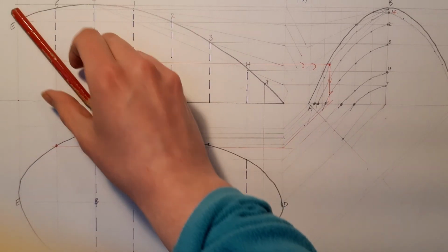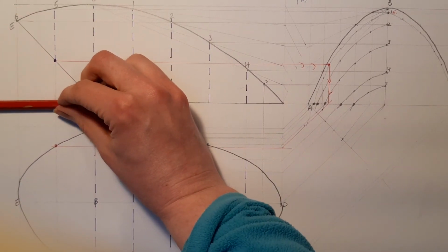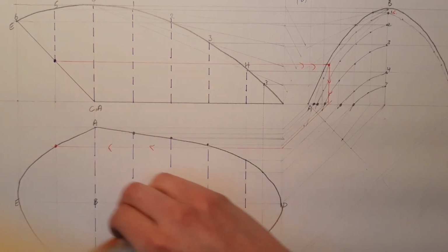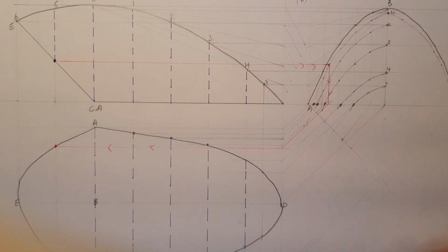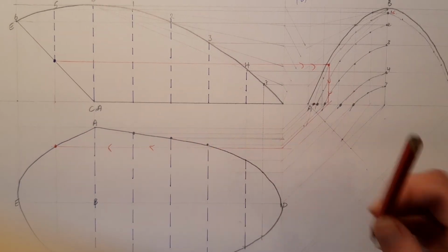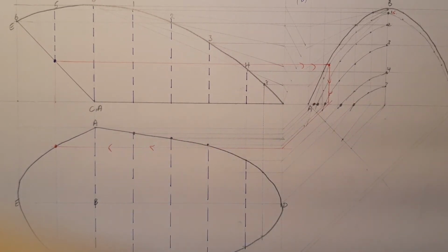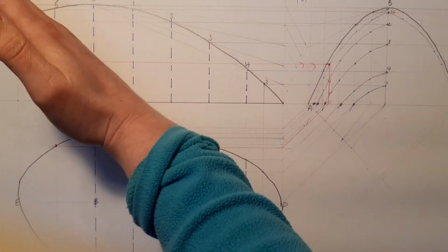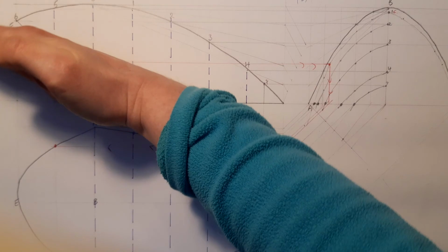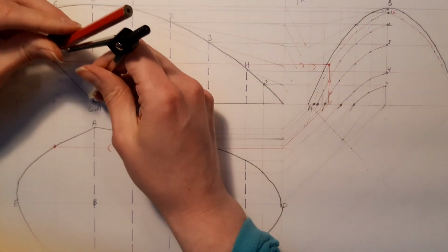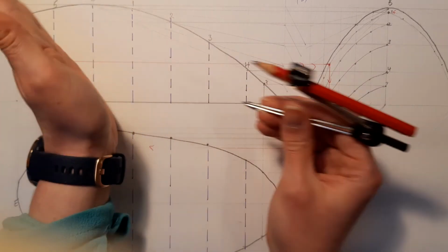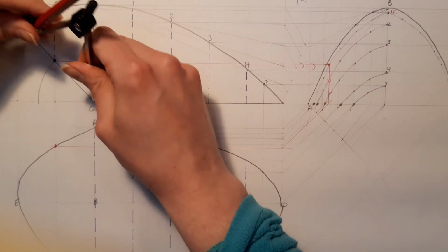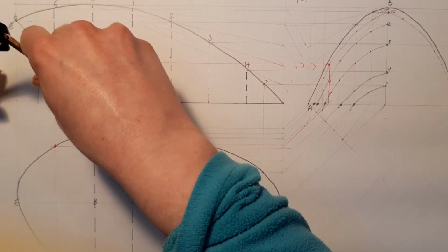If you want to, you can rotate this down and bring it down into plan, and you can draw the plan or the true shape of it directly on top of it, or you can go to one side, it doesn't matter. So I'll do both to show you what you're doing really. Basically, to get the true shape of this, we can do rebattements, which is rotating it down, or we can do an auxiliary, or we can draw it to one side. There's a couple of options. So what I'm doing is knocking this down flat to get the true positions of them.